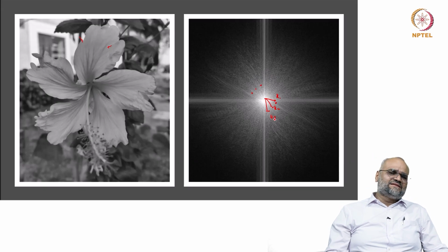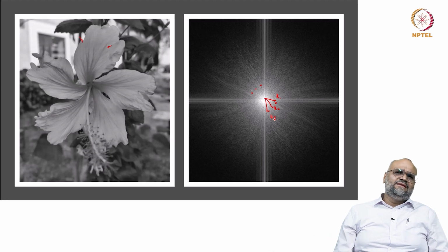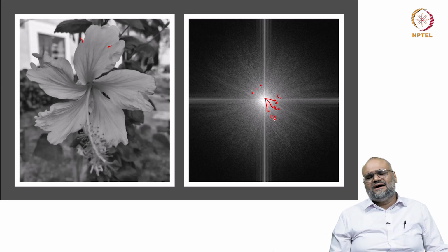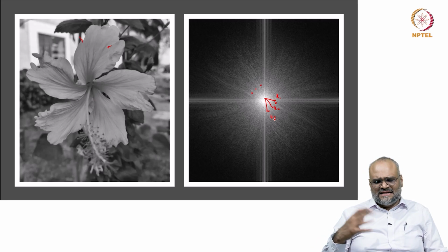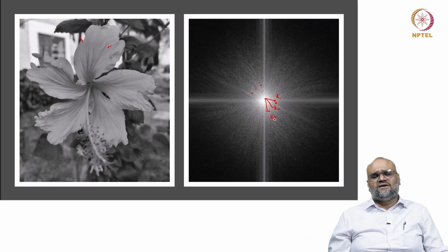So this kind of bridges the gap between the periodic patterns that you record in a high resolution image and the diffraction pattern, and the diffractogram or the fast Fourier transform you obtain from a periodic repetitive structure that you record in a high resolution TEM micrograph.